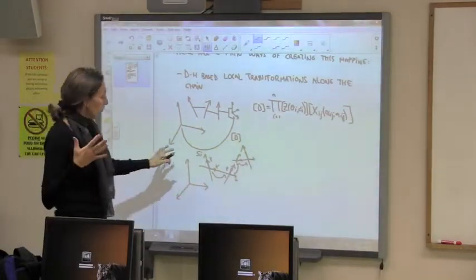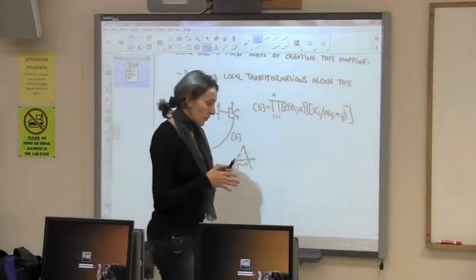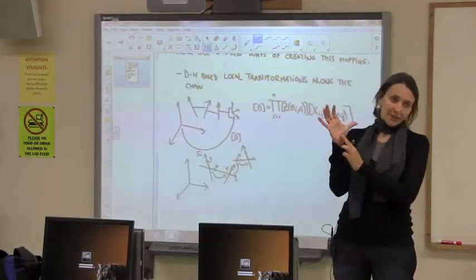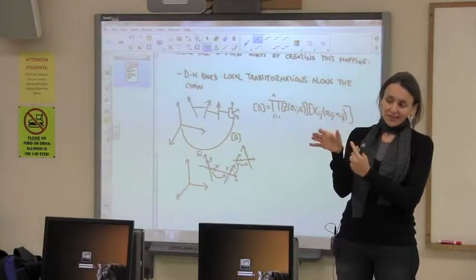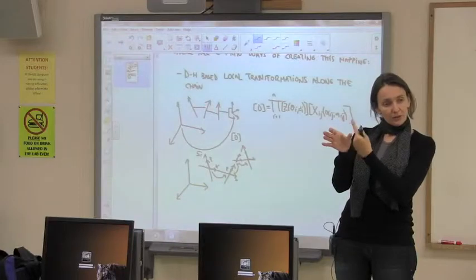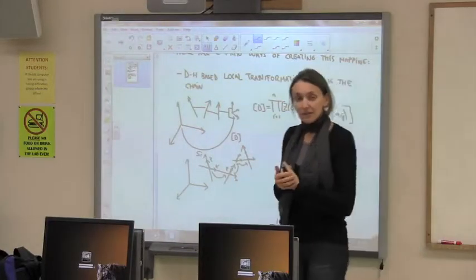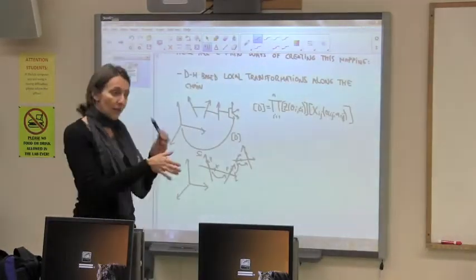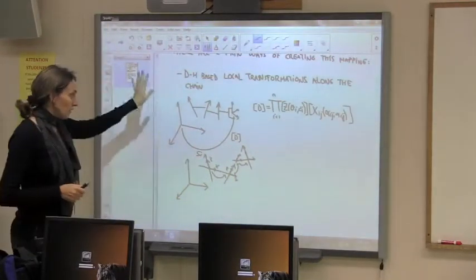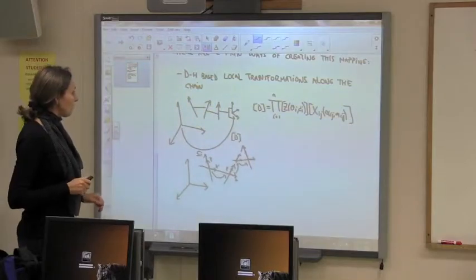For instance, and we have faced this problem before, if you want to write the Denavit-Hartenberg parameters of the thumb, you are in big trouble because it's really hard. The axes are all skewed, and it's hard to give values to those angles in 3D. It's much easier to just locate a line using Plucker coordinates. So that's one of the reasons why we run away from this.